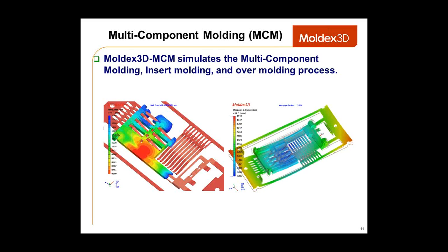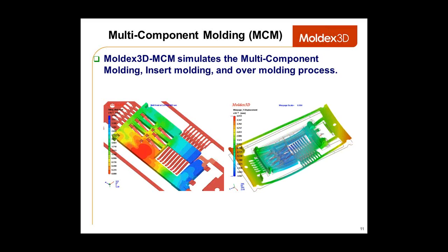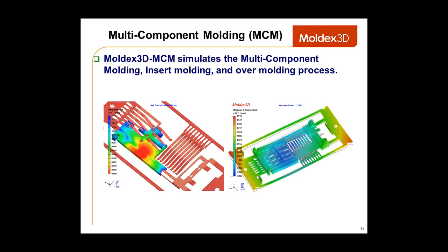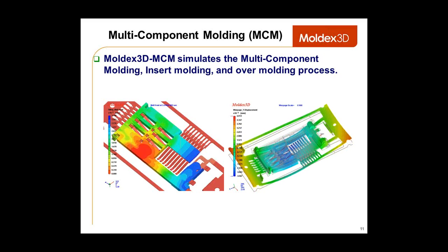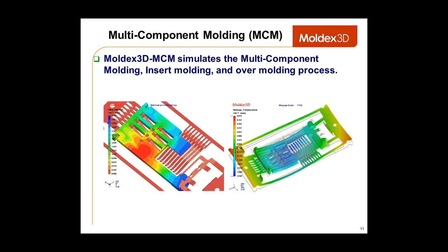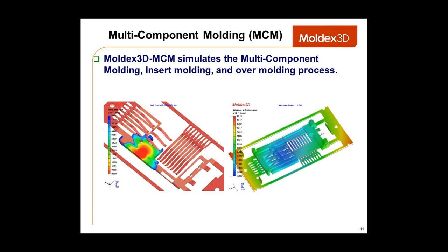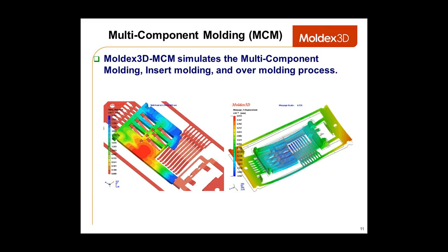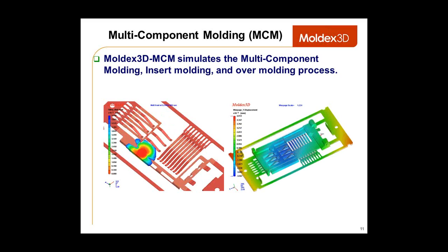MCM, or multi-component molding. With this tool, you'll be able to simulate part inserts, mold inserts, and two-shot molding, also called overmolding. Here we can see the flow simulation of plastic over a part insert, as well as the warpage that is resulting from this flow process.